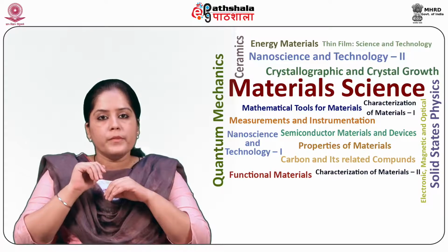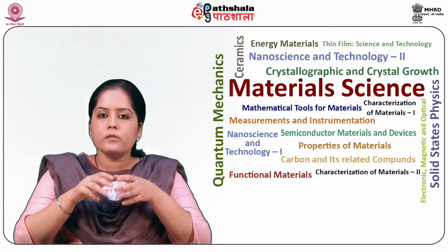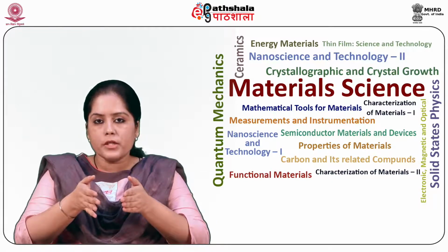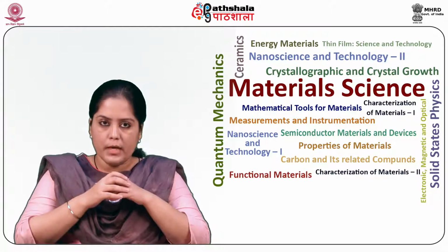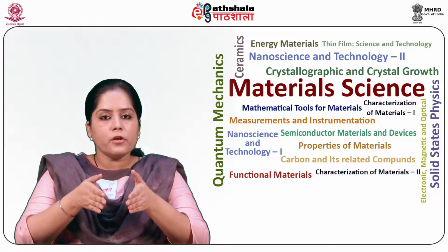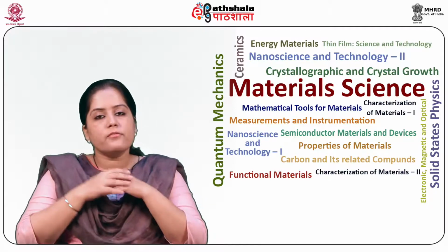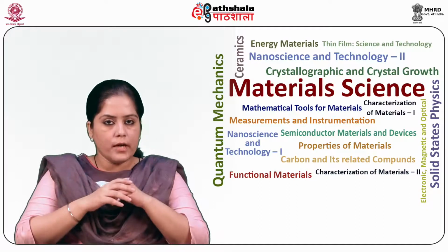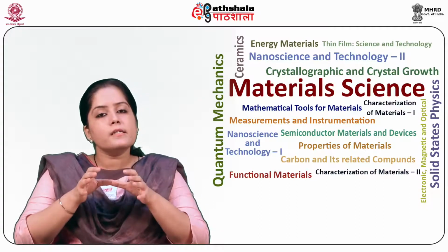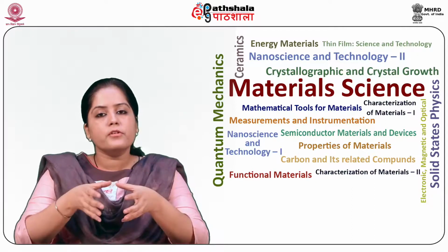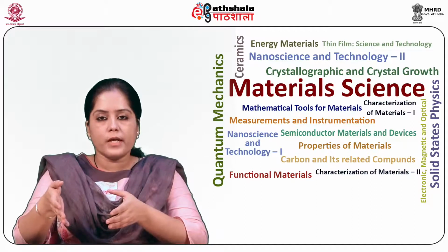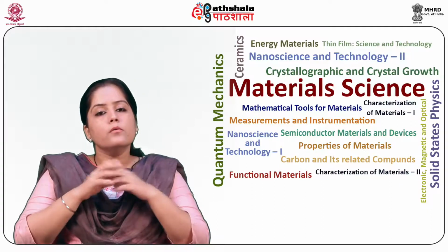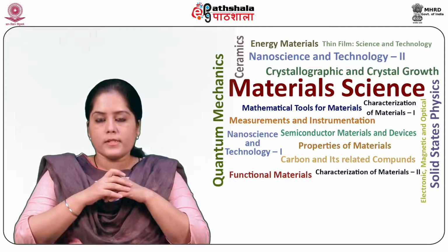So these are material vaporization from a solid source assisted by high temperature or gas phase plasma, transfer of these vapors to the surface of the substrate in a vacuum or partial vacuum. Next is the condensation of the vapor onto the substrate to form thin films. Now, these are the three processes.